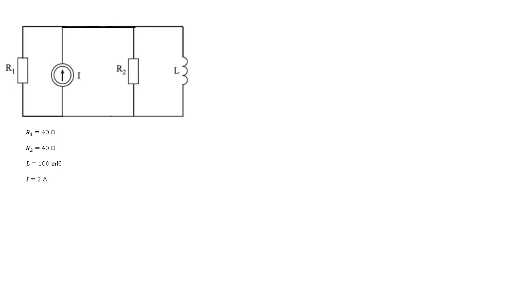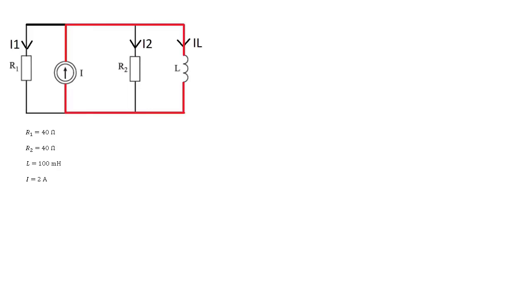We know that for a direct current circuit, the coil is a short circuit, meaning zero resistance, and the capacitor is a break in the circuit, meaning infinite resistance. Current is lazy and will flow along the smallest resistance line, this way. It goes only here, avoiding the more difficult trails with resistors on the way, simply because there is a short circuit here. We can take into account that current 1 and current 2 are equal to 0, and the coil current is equal to the entire current produced by the current source, which means 2 amperes.